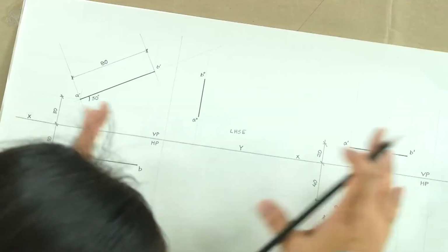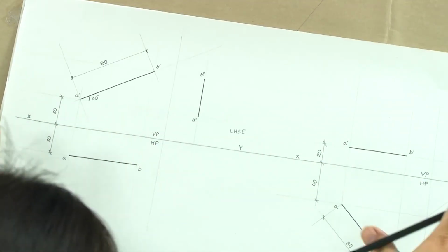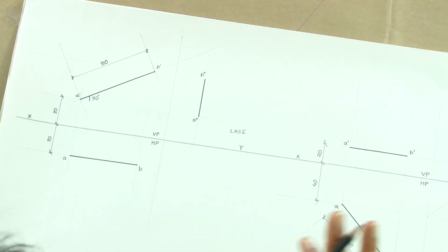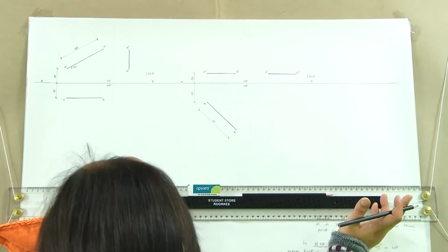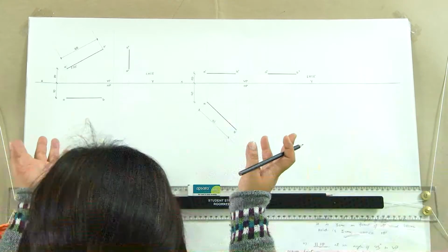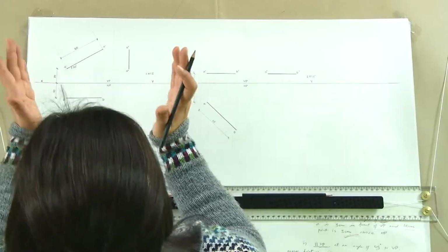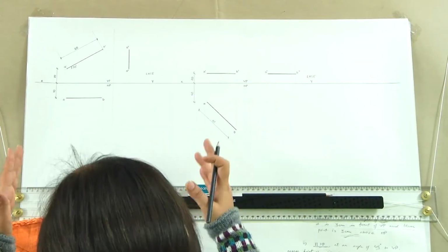Here I have made it continuous. However, if you have say 4 problems to be drawn on one sheet, you should first see how much space each problem would approximately require, and then divide the sheet into 4 equal parts, or unequal also in case one problem requires a bigger solution, and then you should center your drawing in that space available.